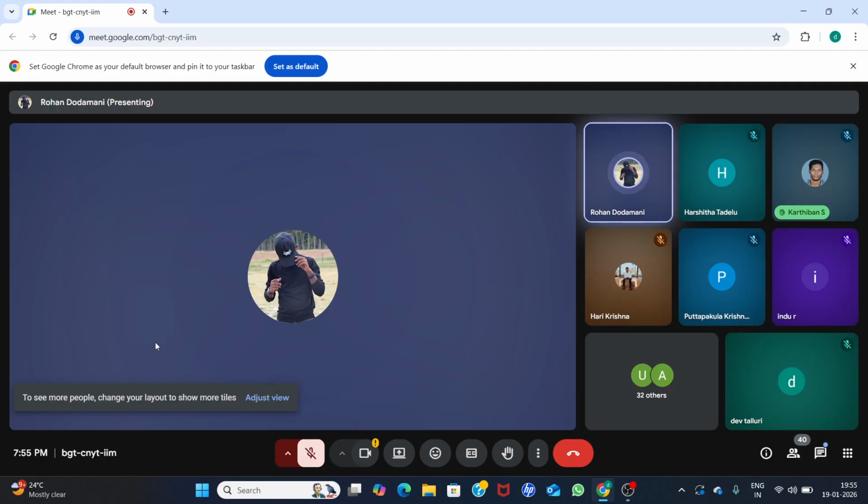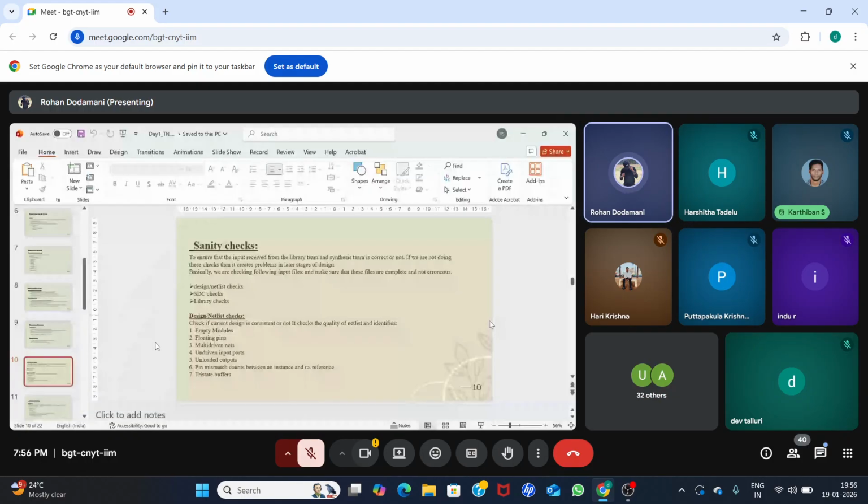Using a full adder thousands of times in our project. So 1,000 full adders are there, but it is not possible to give the same name, full adder, full adder, full adder. We need to give names like full adder one, full adder two, full adder three, right? If we give full adder one, full adder two, then the inputs are A1 B1 for one, A2 B2 for another, A3 B3, like that.